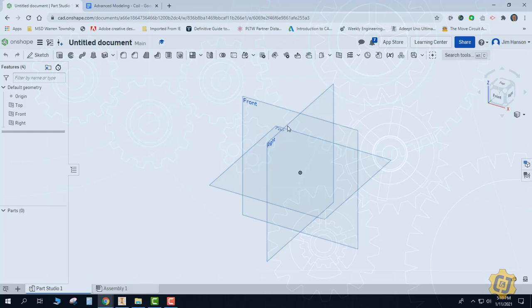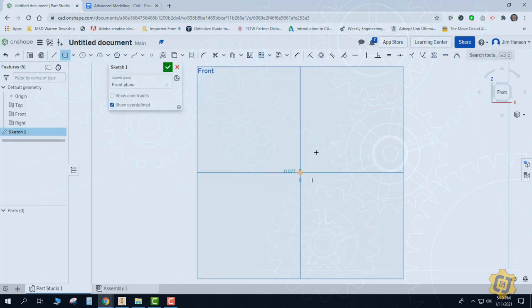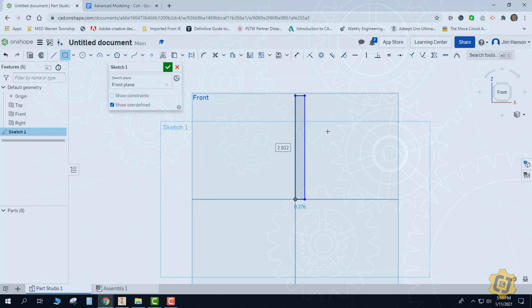Okay, so to start this one off, we know we have a cylinder in the middle and the cylinder gets to stay. You've already seen that we've got 2 easy ways to make a cylinder. I can draw a circle and extrude it, or I can draw a rectangle and revolve it. Because I'm going to go ahead and put the profile on the edge of that, I think I'm going to do it as a revolve just to maybe save myself a sketch. So that's the body of the bolt.